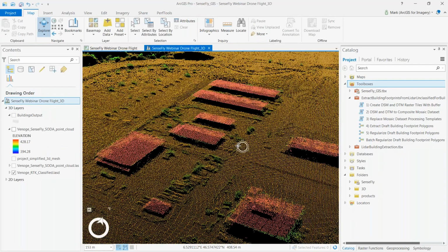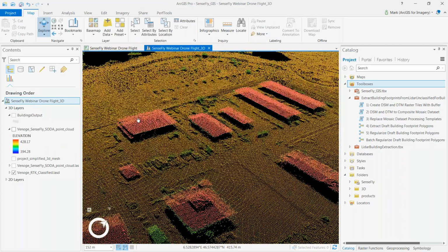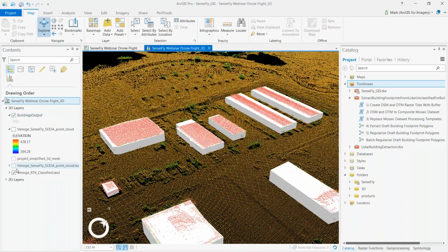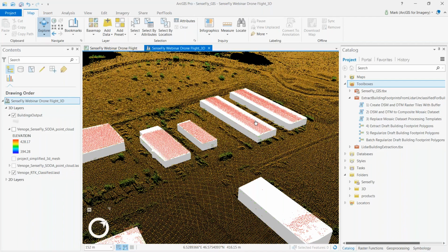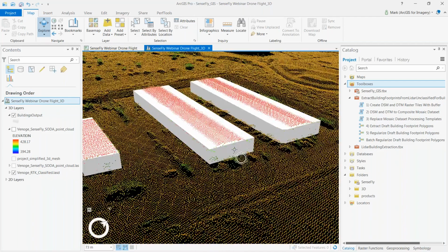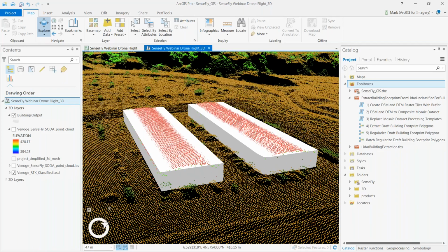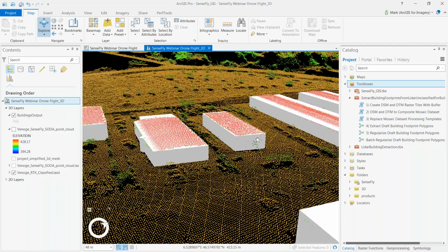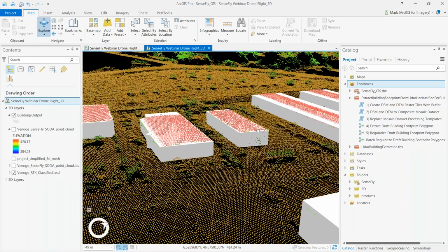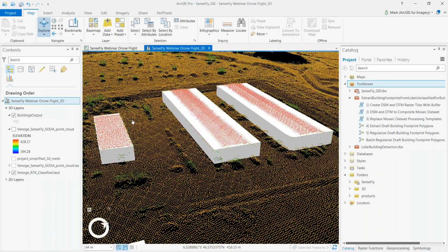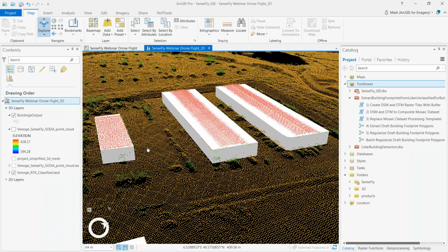I've then taken that building layer, used that as an input to classify the points as buildings, and then with those we can easily generate actual building footprints. So what you're looking at here are the actual building footprints that I've gone through. And at the moment here, these look like just, you know, bricks or rectangles. There's another workflow that's part of the local government solutions that factors in the pitch of the roofs and lets you really get a more detailed or more accurate representation of the building model. So I just wanted to walk through those.